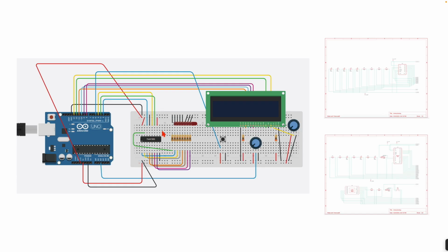And similarly, there are 2 grounds. And then we have our 8 outputs here, which go into these 7 ports and this port. These each go through a 100 ohm resistor to protect the LED, and then through the LED and into this ground chip here, which goes back into the board.